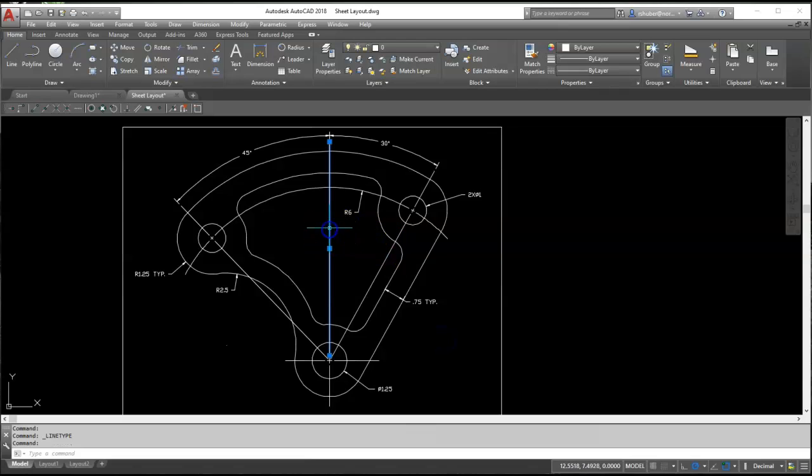So now what we do is we select this line, drop down, and we can make it center 2. And take a look at what happens. It automatically puts the dashes in there for us. So let's click on this arc here, drop down, make it center 2 line type. Click on this one, drop down, center 2 line type, puts the dashes in for us. Click over here, drop down, and we have our center 2 line type. So if I click on this, you'll see that it'll show up over here. If I click on the object, it'll just be the same by layer, which is our default.